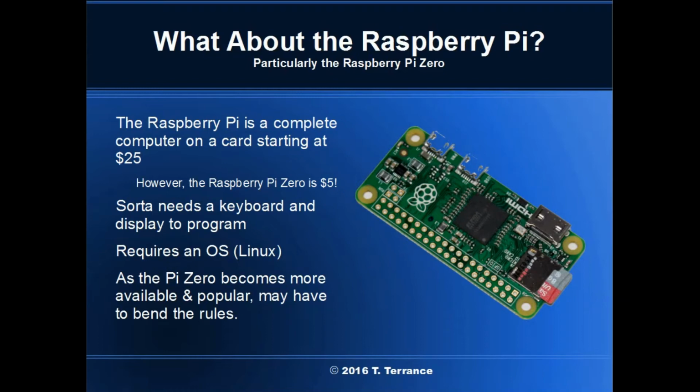The Raspberry Pi Zero W, at anywhere near the list price, opens up the prospect of wireless layout control. Conceivably, it could eliminate tons of wiring below the layout. Imagine layout command control passed wirelessly from node to node. Because all Raspberry Pis boot from a micro SD card, providing pre-programmed micro SD cards takes care of any programming issues. This deserves further investigation.